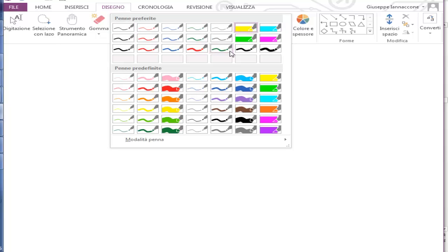So let me write briefly the situation for the PMOS so that we all have in mind the same thing. We have a VTP which is smaller than 0. Then we have an off state if VGS is larger than VTP. Larger means also less negative.